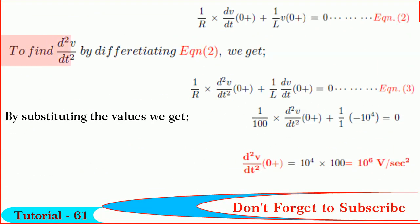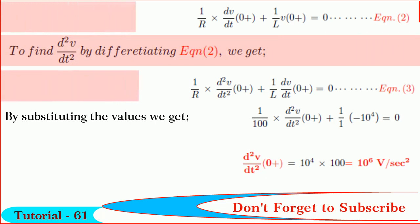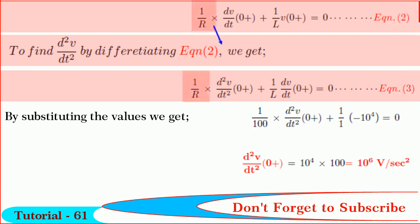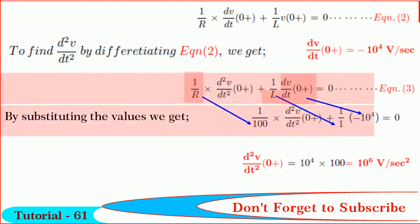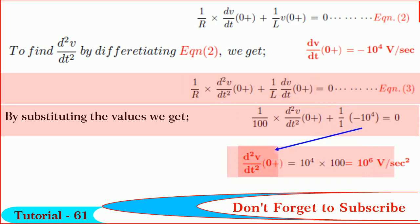To find d squared V by dt square 0 plus, by differentiating equation 2, we get 1 upon R into d squared V by dt square 0 plus 1 upon L into dV by dt 0 plus is equal to 0. By substituting the values and solving, we get d squared V by dt square 0 plus is equal to 10 to the power of 6 volts per second square.